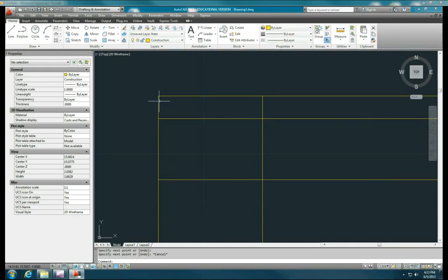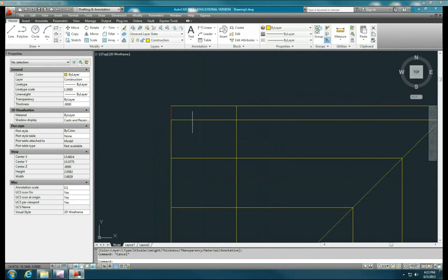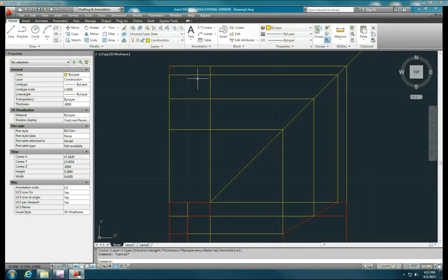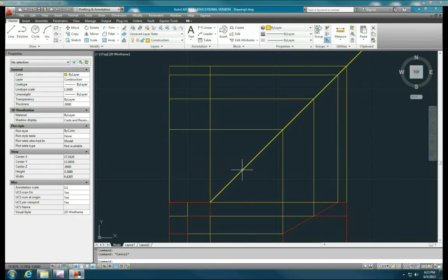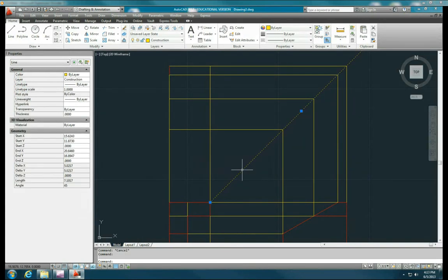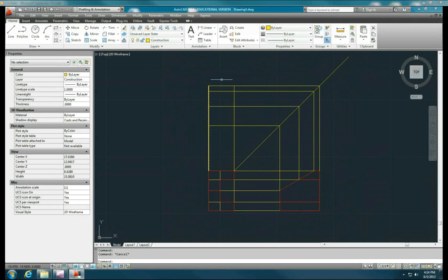Okay, and if I click on it, 0.2431, and it's because this line is exactly 45 degrees. If it's even a thousandth of a degree off from 45 degrees, these measurements won't transfer from view to view. But if this is exactly 45 degrees, this is how you can transfer measurements without having to redo your work up here.